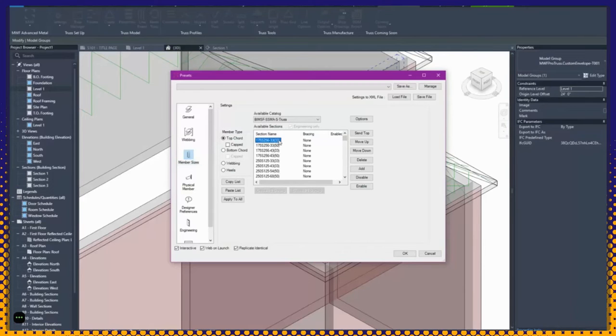So for the trusses, I can actually come in here and say, you know what, I'm going to be building everything to be either 400 or 600. So I'm going to delete everything up here. And then I'm going to go ahead and delete, maybe I don't want the 162s. I only want the 200s. I can delete the 400 S162s. You have to make sure that you load in your families prior to even coming into this step. Otherwise, they will not show up on the list. Okay?